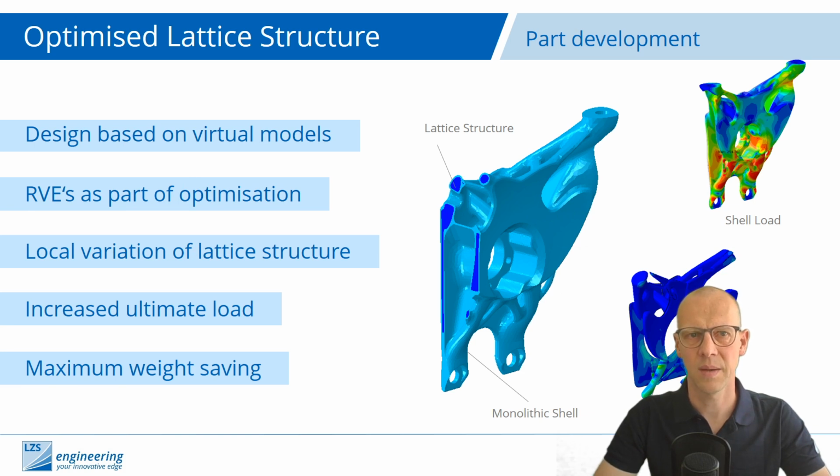And this we did. Here we designed a bracket structure. The bracket structure was planned to be used as a load introduction feature for a hydrogen tank. And when you do some kind of topology optimization, you will end up with such a biological or bionic shape. And the good thing with additive manufacturing is that these shapes are manufacturable for the first time, and even as a hollow structure, as you can see here.